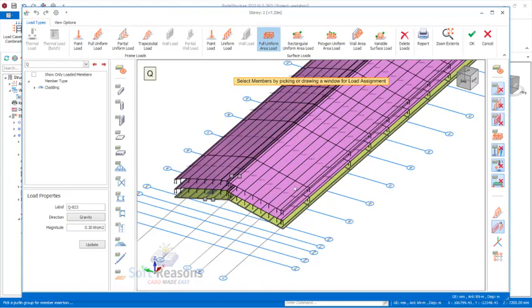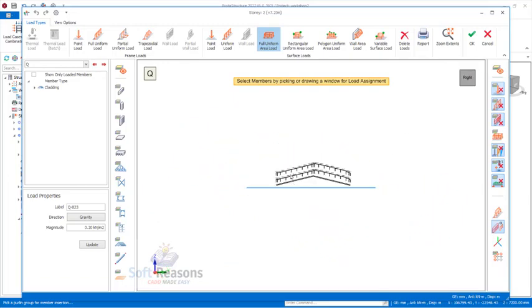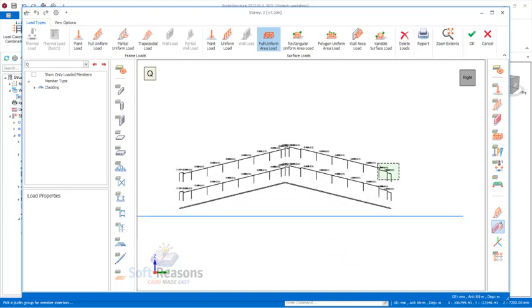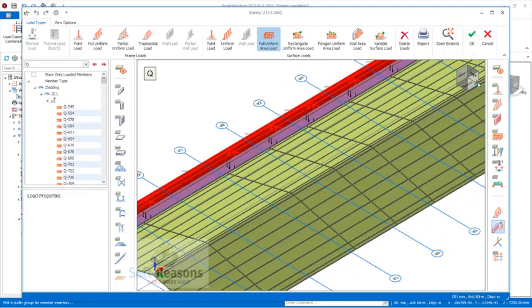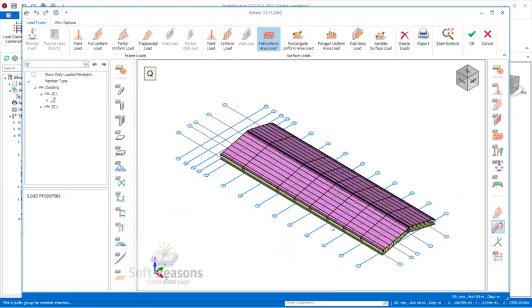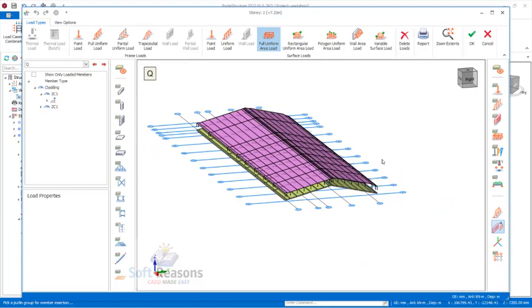The load is in 2 layers as well, so you can easily get back to the other side using the cube navigator, so that you will not overload the structure. These loadings depend on your own calculations. Hold down the control key to be able to select multiple of the second layers of these loads, after which you can navigate back, right click and click on remove to have only one. Now having successfully loaded the roof, we click on the OK option.